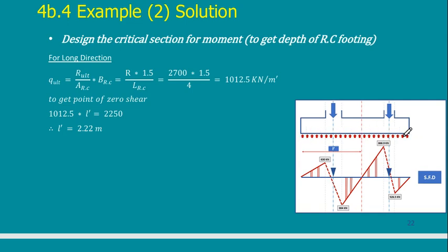But why am I going to calculate this reaction? I'm going to calculate this reaction to get the bending moment and the shear. What am I going to use the bending moment and the shear for? I'm going to use them in the design of the thickness of the footing. First, the bending moments will be used in calculating the thickness of the footing and the amount of reinforcement. Here I use the code for reinforced concrete.